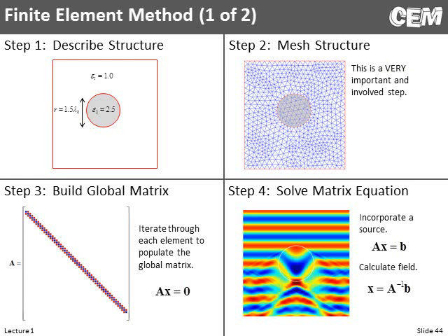Finite element, you probably have at least heard of this. And there's actually an additional step in here over the other methods, because there's this whole meshing thing. You have your device, and the first thing you have to do is mesh it. Now you describe it with all these triangles. And in fact, many times that's the slowest part, is just the meshing, figuring out where all the triangles have to go. Once you have that, then you go ahead and you build your matrices and you solve them and you get the answer to the problem.